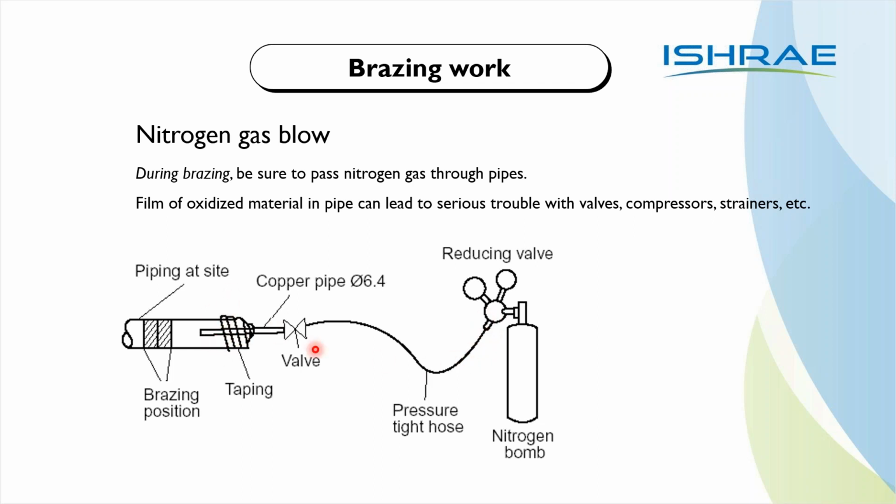So when you are heating this pipe, this nitrogen keeps blowing inside, and any amount of carbon deposit that can get inside here gets blown off by the flowing of this nitrogen. So this process is known as bleed off brazing. The process of allowing 2 to 3 psi or 4 psi of nitrogen into the pipe you are brazing is known as bleed off brazing.